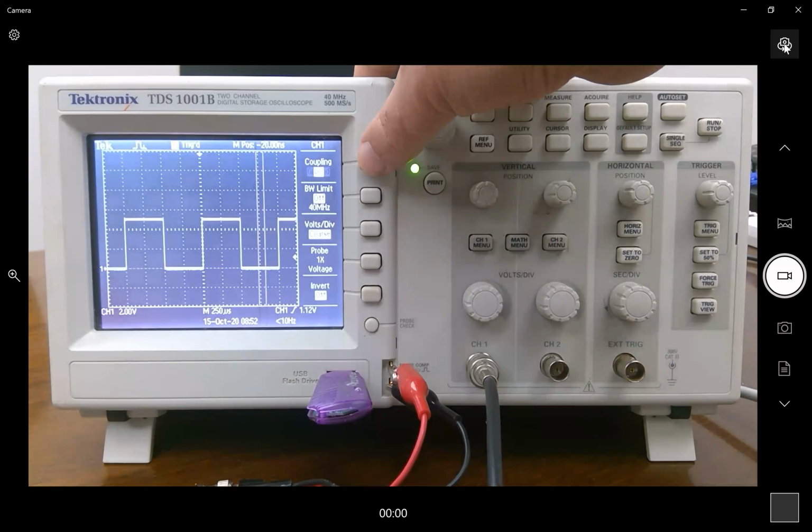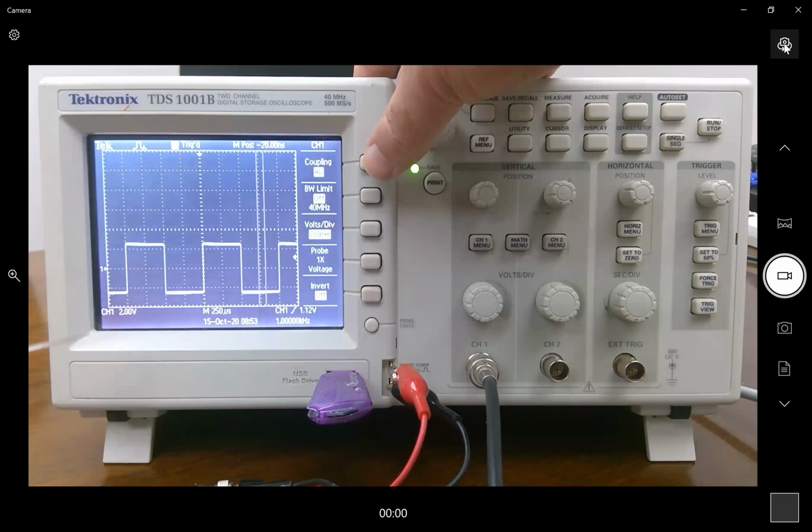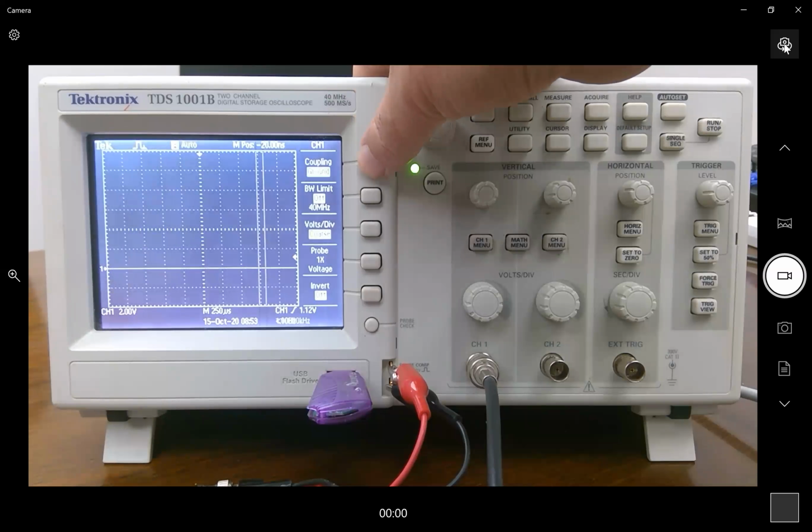That's not a problem. We go back to the DC again. Now it has a DC offset of 2.5 volts. And when I get rid of the DC, it drops down, and now you've got what looks like just a square wave, kind of like a sine wave or something like that. So we'll go back to DC.